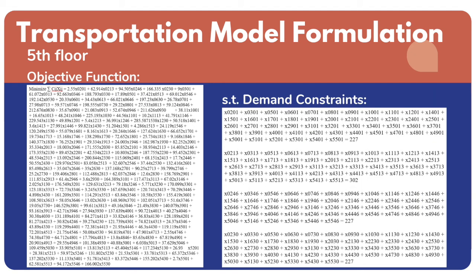This slide then shows the demand or capacity of the exit stairs constraints. We inserted capacity constraints on each exit, even though the behavior of evacuees is to go down continuously, to limit the people going out of the exit doors, since there is going to be congestion once the people are not allocated properly and evenly to these exit stairs or doors.